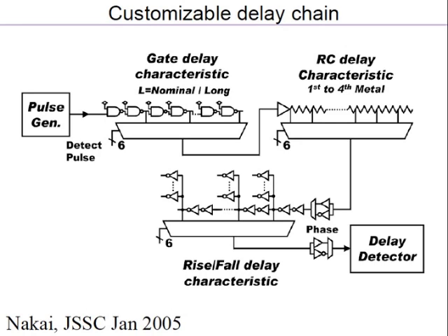You will have to live with some margin, but that margin is hopefully small, so that by measuring this and adjusting the voltage, you can say that this meets the delay you want. Suppose you have a frequency target of 1 gigahertz, which means a 1 nanosecond period.